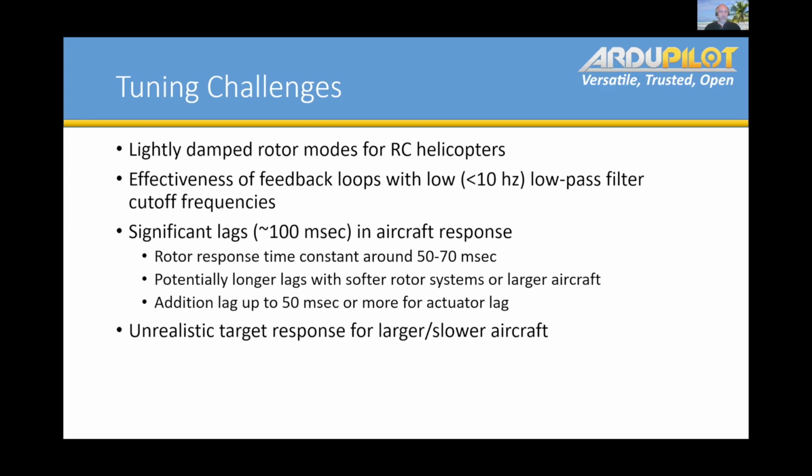One of the other things is, we had a lot of these vibrations coming through that would mess with the effectiveness of the feedback loops, because you saw that your signal really had a lot of noise in it, and so you had to reduce your low pass filters down to some really low cutoff frequencies, which then adds lag to the system. So that was one of the things that I felt was a challenge.